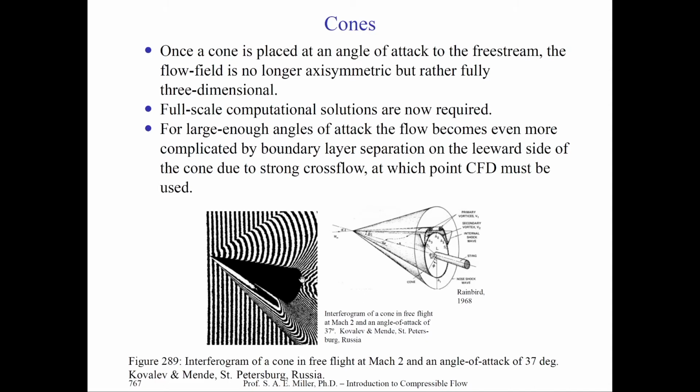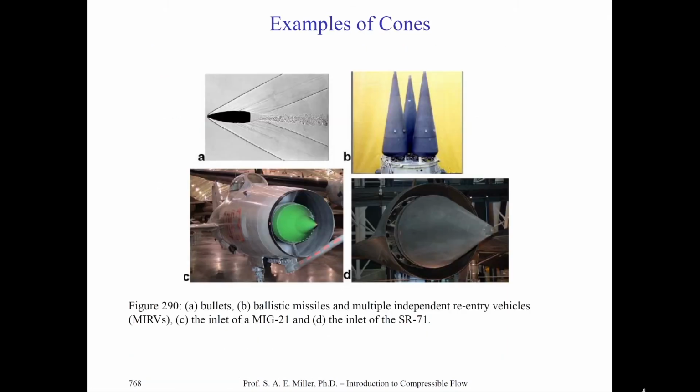Once again, of course, there is this high-speed shear layer, which you see here with these strong angles of the zebra striping above and below the cone and a turbulent wake behind it. It's a beautiful picture and a very, very difficult problem to analyze that people are even doing research on today to understand and study. Let's look at some examples of these particular cones where you have attached conic oblique shocks.